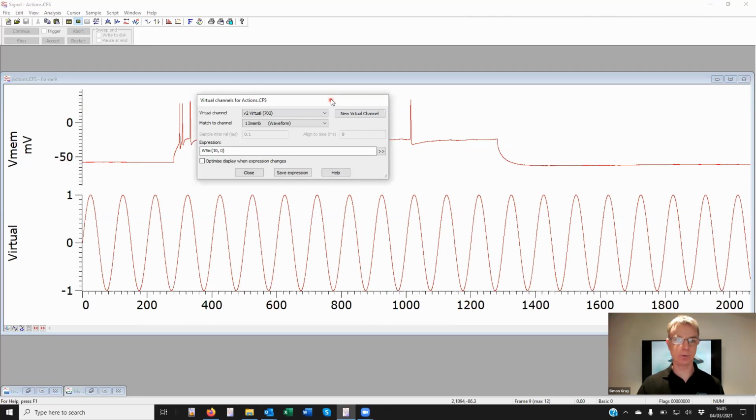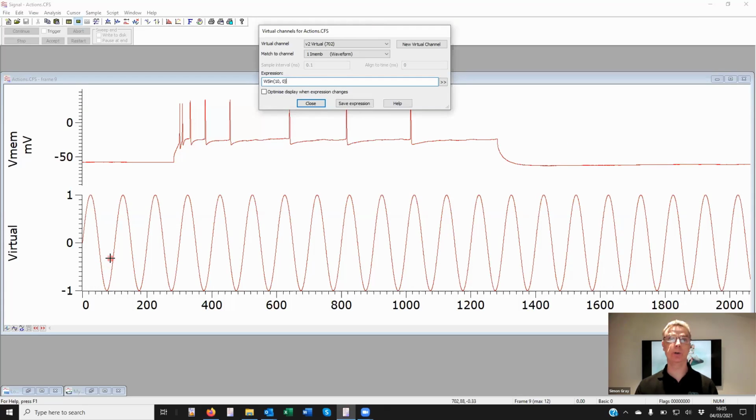Now, the problem with playing this out, and I use this in auditory experiments quite a bit for playing tones, is that with a simple sine wave like this, at the start and end of the output you tend to get a clicking noise as you introduce new frequencies when the waveform starts and stops.